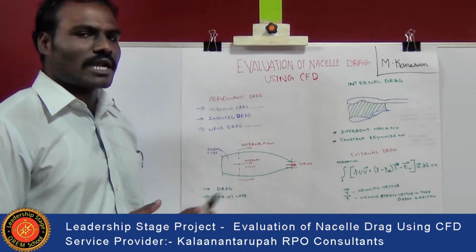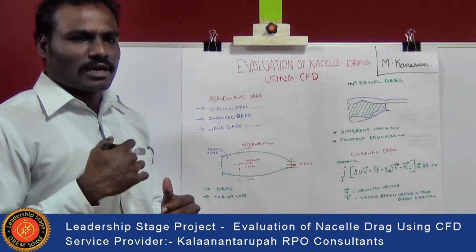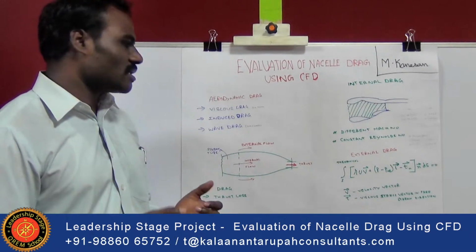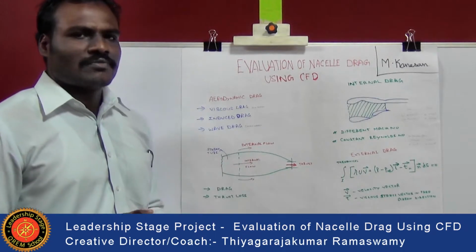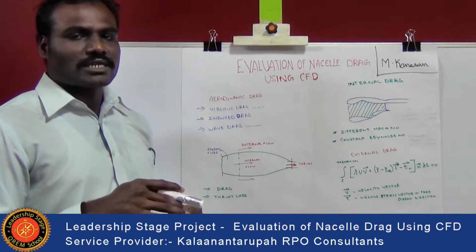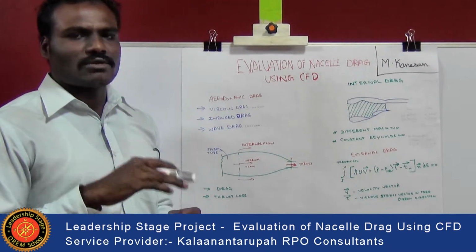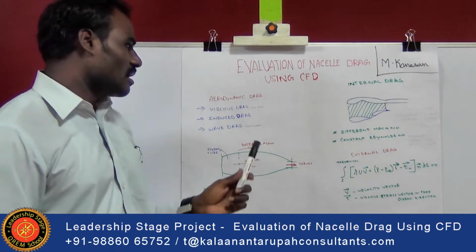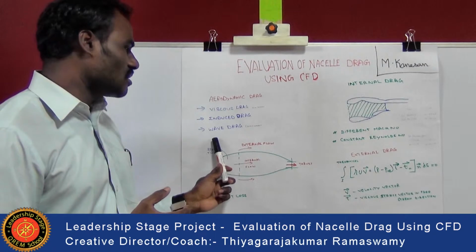Whereas induced drag consists of a variation in the distribution of pressure over the nacelle. In wave drag, the pressure distribution as well as the shock waves acting over the surface, that is the external area of the nacelle, are studied.